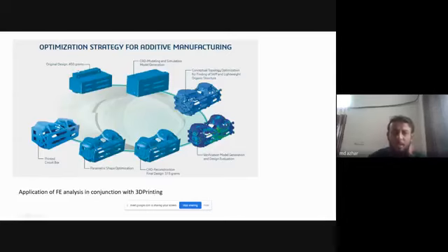Something you can see, this is the original design of a model. This whole thing is 450 gram, and finally after doing the finite element optimization, the final design you get is this. Then you print it using the additive manufacturing process, and the final design after the CAD reconstruction is 315 gram.